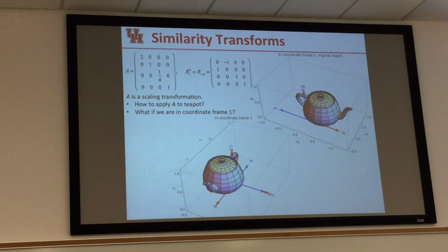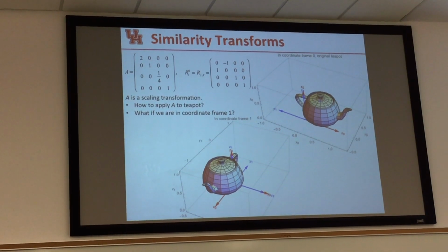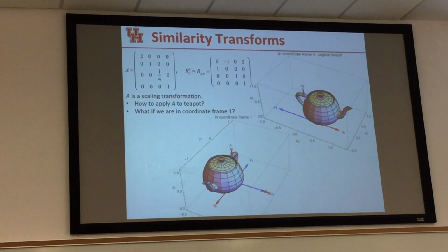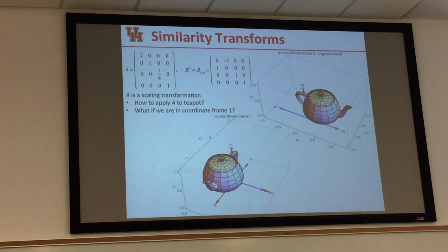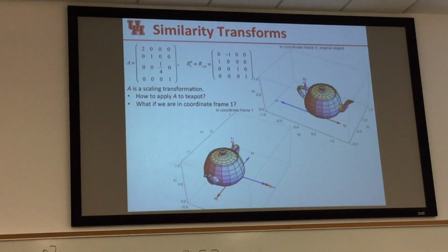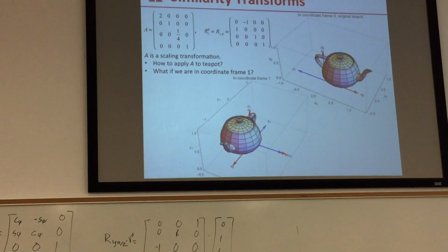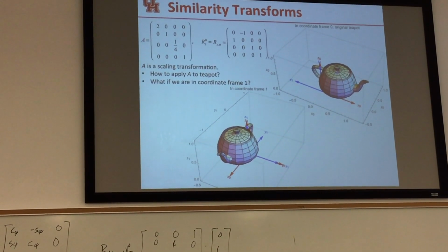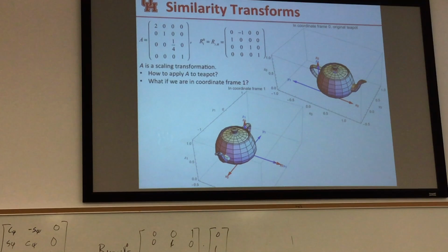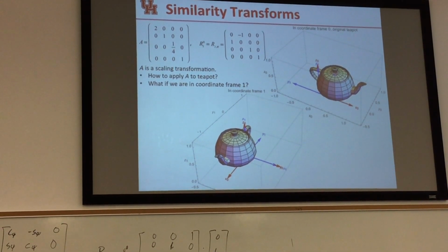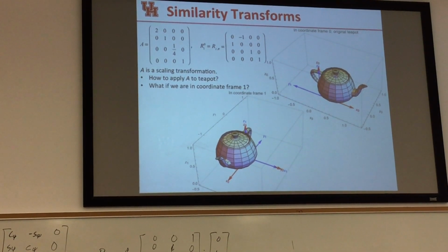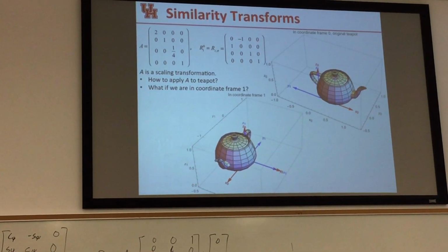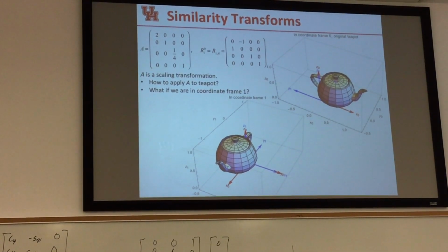The fourth element there? That's a good question. So this is a hint towards the future. This is what's called a homogeneous transformation, in that it not only rotates, but it can also translate the object. And so we are going to be using 4x4 matrices by the end of the lecture. The top 3x3 matrix is a rotation matrix. The last column is a translation column. The translation ones in this case are all 0, so all it's doing is a pure rotation. But excellent question. That's what's going on here. We're going to hit this a lot later.